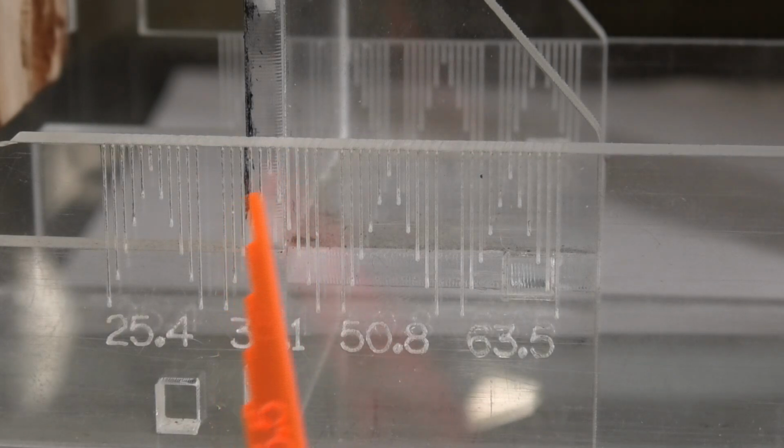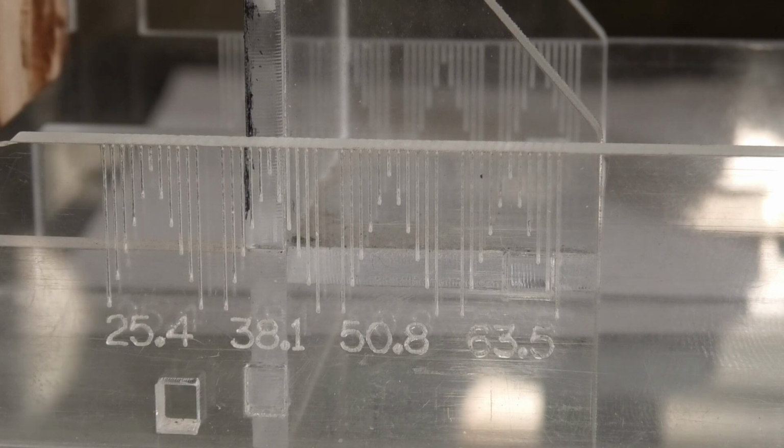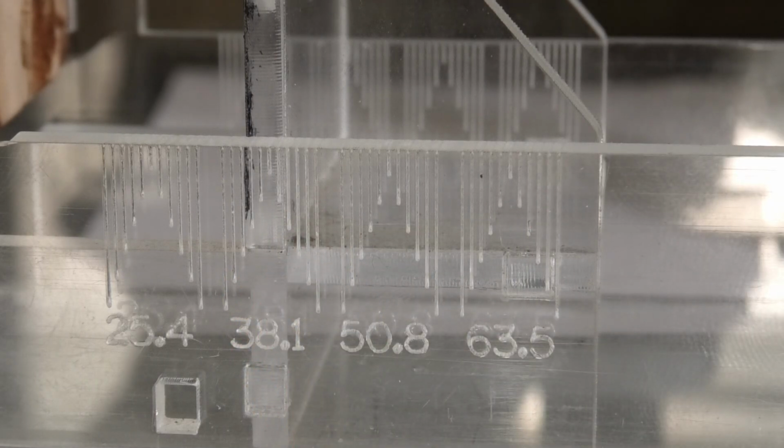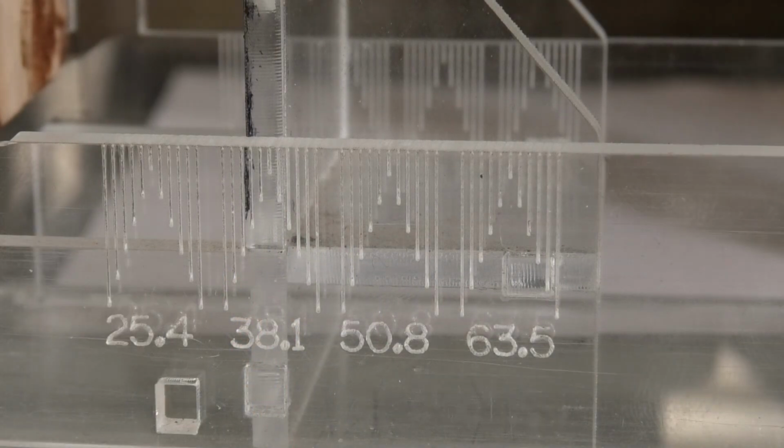It's probably about maybe 2 or 3 millimeters out of focus, but that's because we're looking at this lens with normal light. Its focal length is designed for use at 10.6 micron wavelength light, so it will always be different than what you can see with the naked eye. So don't get worried if you don't get a perfect match. It's one of these 4 lens types, so whichever band this happens to be in, that's the lens focal distance that the manufacturer claims it to be. The wavelength of light can affect the focal distance.